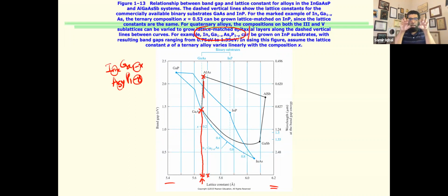So if you put one layer of atoms which are maybe this distance apart, and you put something on top of that which is a bigger distance apart, there's going to be a problem. We'll see that problem in the next slide. But I want to show that with epitaxy, we can put down a bunch of different materials on the fly during the epi process.